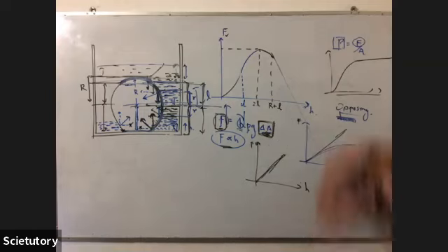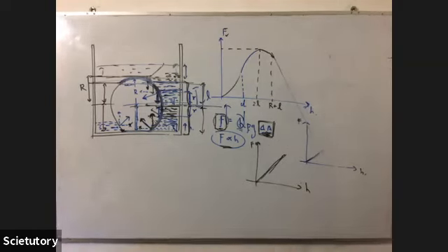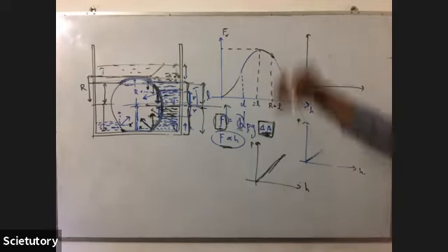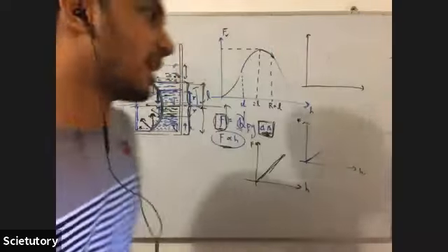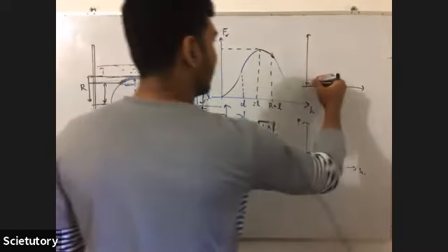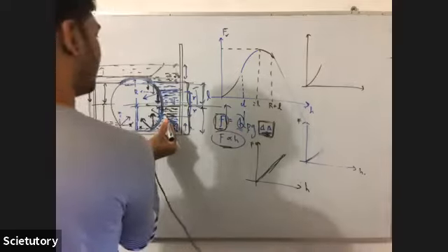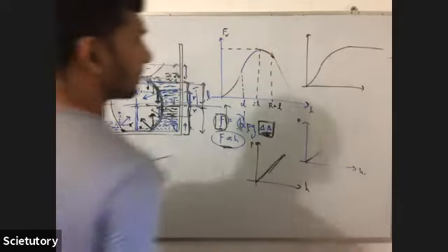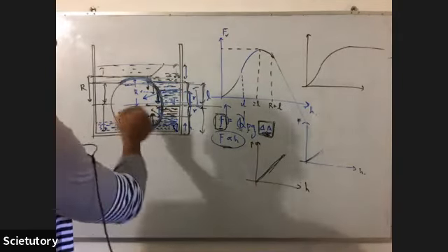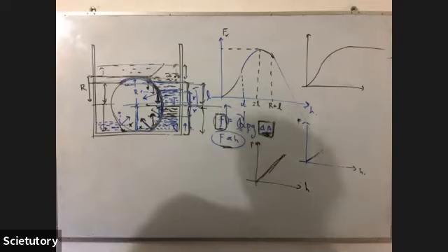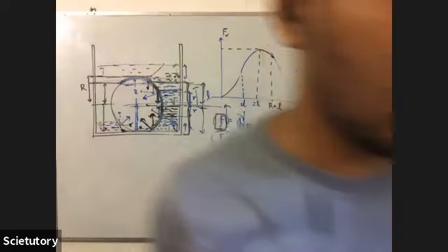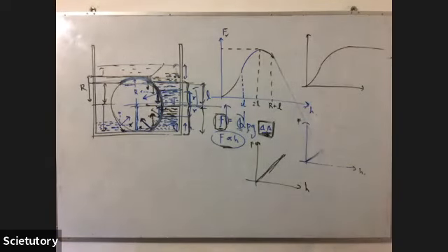Excuse me. Wait. The answer would be like this if it is a sphere just placed hanging, like I explained in the cylinder example. For this part, you will have this kind of graph, and for this part, you will have this kind of graph, and then it will not change. Always the lower parts will overwhelm the upper parts, because the depth is always higher for the lower part of the sphere. So it's constant, and that's the upthrust, if the object is a uniform sphere.